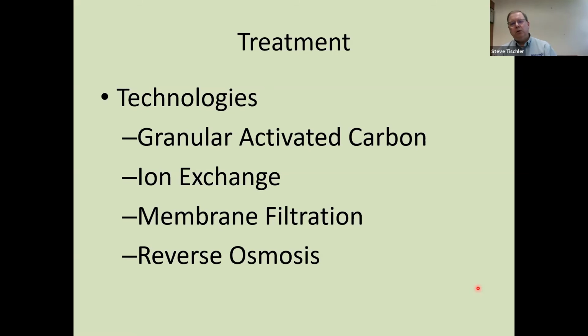water. Now, the issue associated with this is that they can remove PFAS chemicals from the water, but they haven't eliminated them. Okay, as we had said earlier, they're forever chemicals. So if you use granular activated carbon to remove PFAS, you've got PFAS contaminated granular activated carbon, and you've got PFAS contaminated ion exchange resin, and you've got PFAS contaminated RO discharge. So you've certainly not eliminated PFAS from the equation. You've just effectively removed it from the water that you might be treating. But these are all very effective technologies for removal.